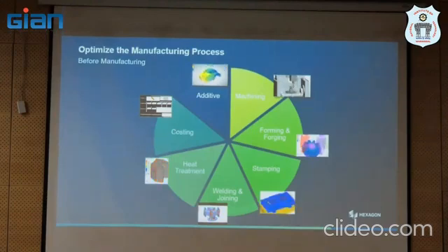First I will create a digital twin, in the sense that I will create the same set of environment. Then I use a couple of sensors to monitor, let's take a machining process, what my spindle speed is. I can put one sensor, understand the rotation speed and make it visible in the software, so that it becomes live monitoring, the digital twin connected to the machine. Then we have other software where we can simulate and understand the material flow, the loading condition and other stuff. We can also do conventional processes, welding, joining, and the effect of these processes.